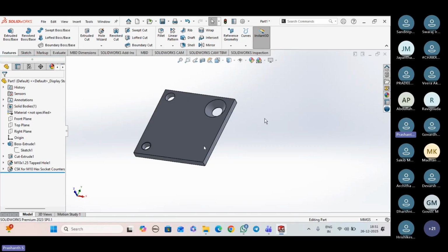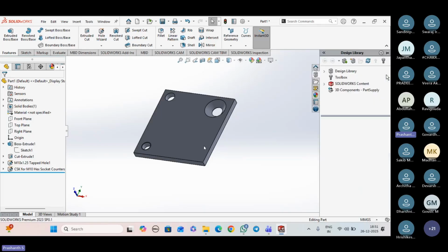See, in a standard gear, everything is defined, right? So there is no need to make that gear from scratch, like making a circular disc, generating that profile, and then giving the angle, the teeth, and all those things. It is hectic. So for that also, we have some standard toolbox. But for now, we'll just explore where the fasteners toolbox is. If you see in the rightmost corner of the window, you will be having this palette. Inside that palette, just go to Design Library.